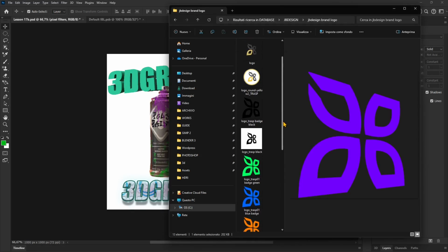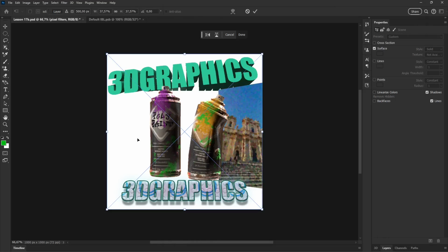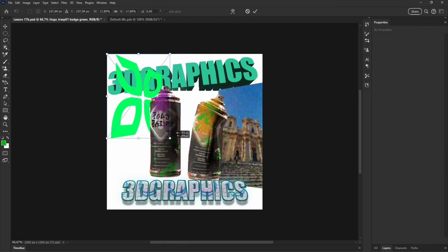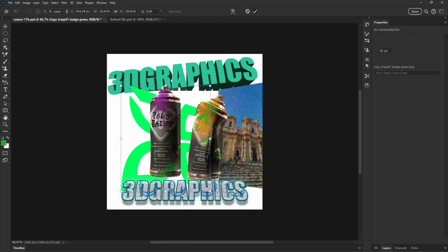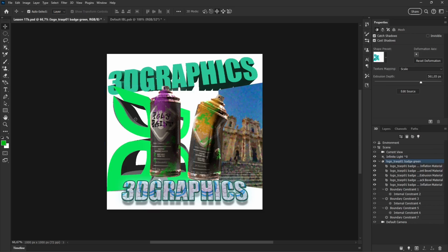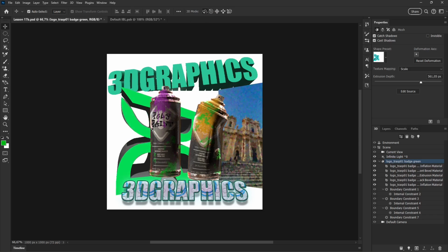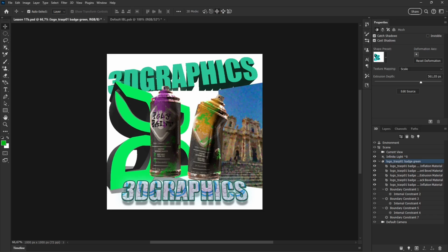And you can do that also with standard transformation. If you have a PNG, so you don't have a background, like this logo here that I have on my computer, I can click and drag, and let's make this a little bit smaller or maybe bigger. So if you have this, let me go back in the 3D here. You can do an extrusion with this, and it's going to create the actual extrusion you see there. So if I now adjust it with the orbit like this, it's not an image, but it actually has the shape of the PNG.